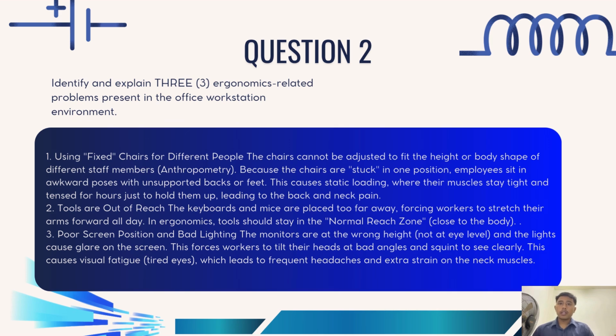The second point is, tools are out of reach. The keyboards and mics are placed too far away, forcing workers to stretch their arms forward all day. In ergonomics, tools should stay in the normal reach zone, which is close to the body.